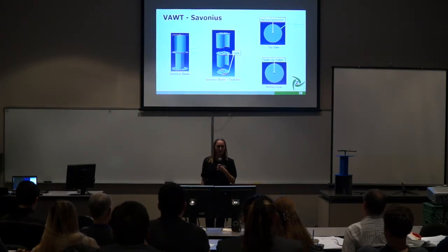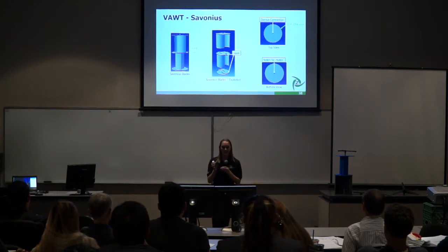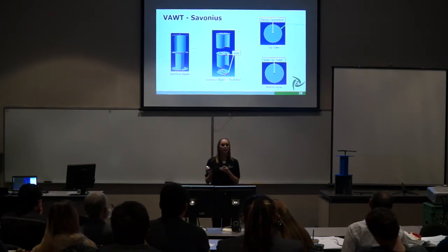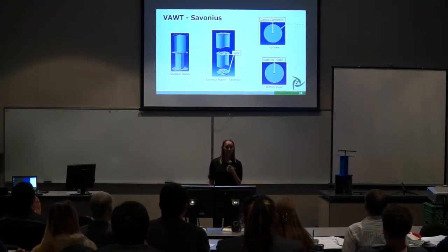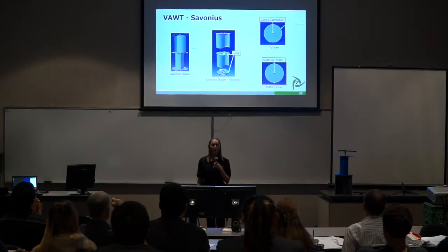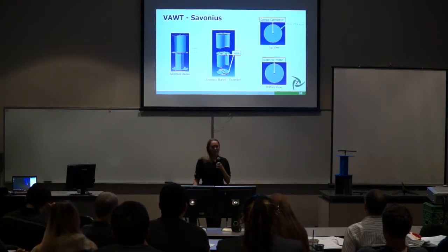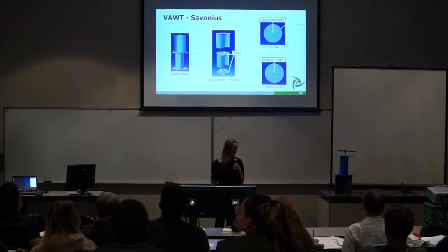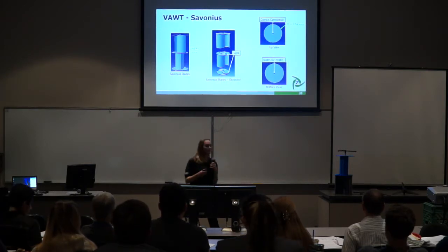The Savonius blades consist of 2 tiers. Each tier has a 90-degree offset from the bottom tier. Each tier contains 2 cylindrical cups facing in opposite directions. Due to the large scale of the part, it will have to be printed separately, as shown in the middle slide.